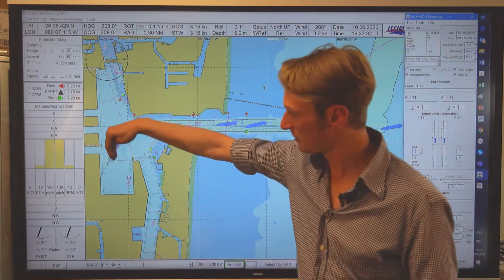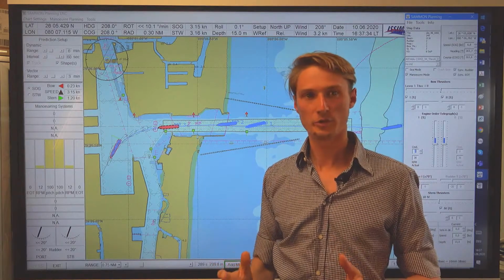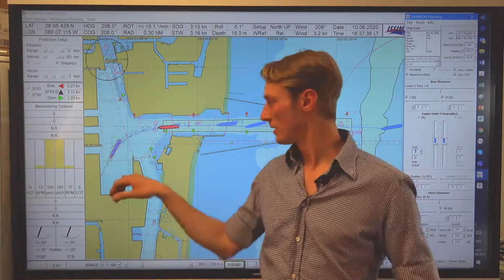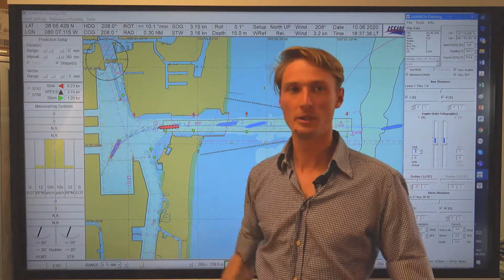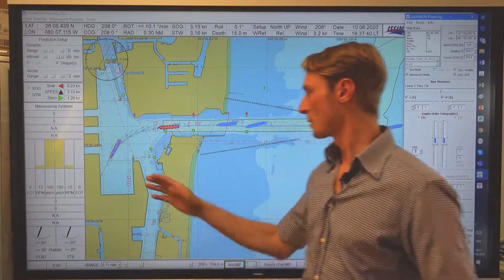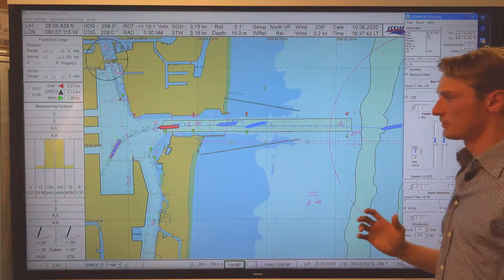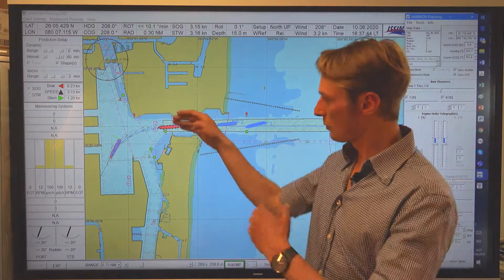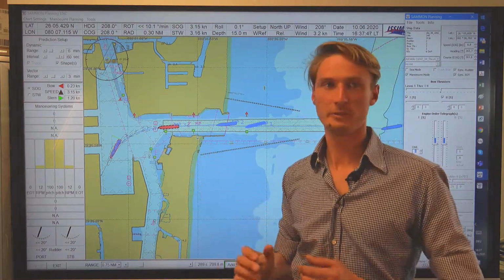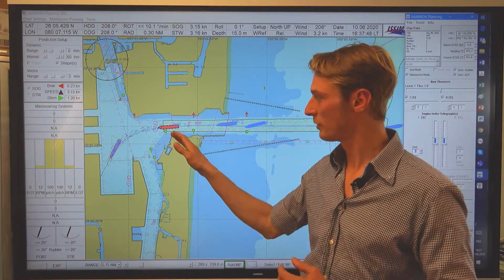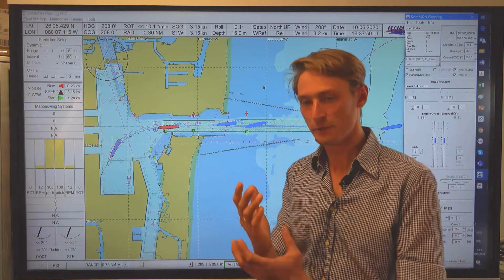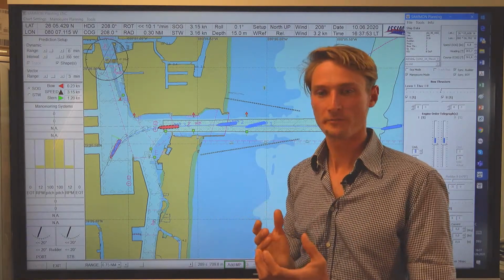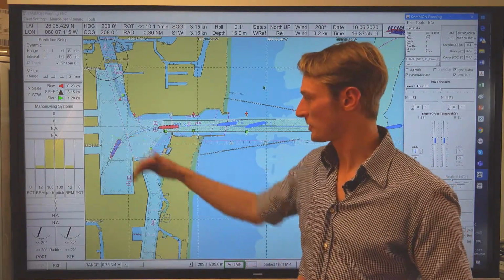So I want to end up in the middle to be in a safe position where I can stop, move to the starboard wing, and then approach the pier by the stern. What we can do, of course, is use the passive steering effect. The rudder is put 20 degrees to port, and we just have the ship's inflow that helps us to turn to port side.